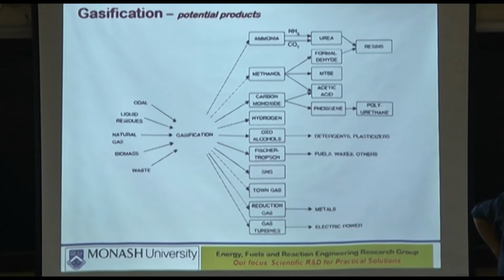So some of the coals which can produce a lot of methane are obnoxious, but there are ways to tackle that methane as well. It comes at some cost. So we'll talk about that too. Unless you cool it down all the way, and then you apply membranes. But then again, cooling down means exergy loss. However you look at it, you cannot avoid a certain amount of exergy loss, right?